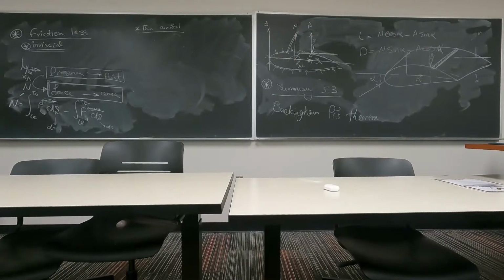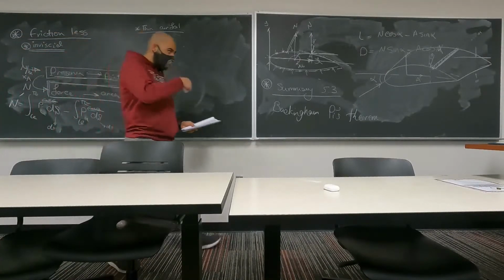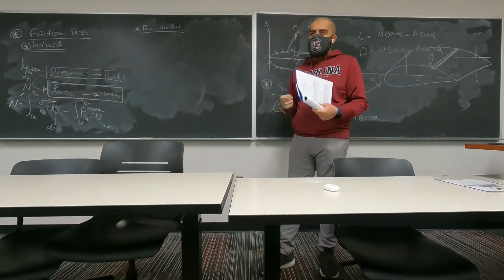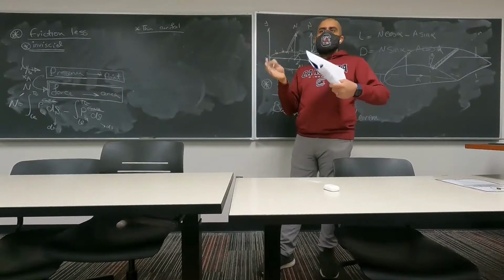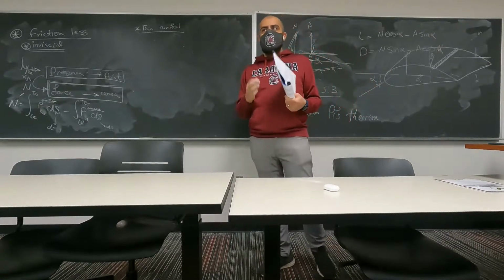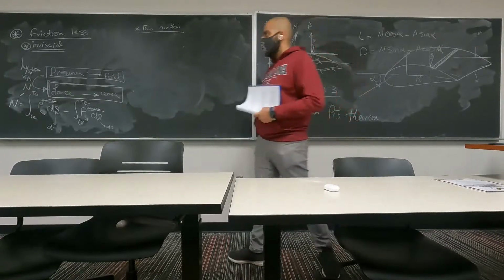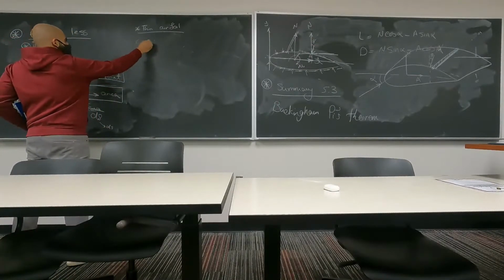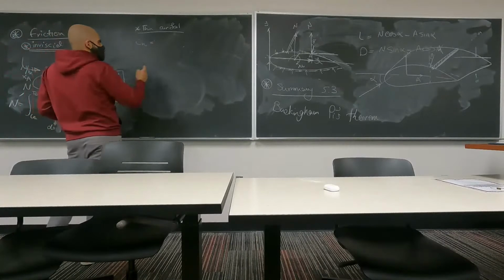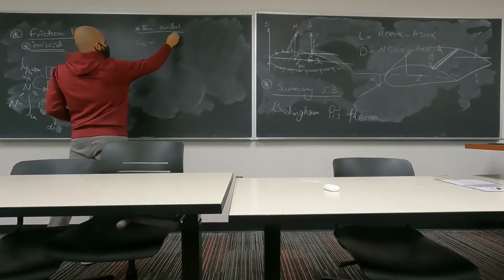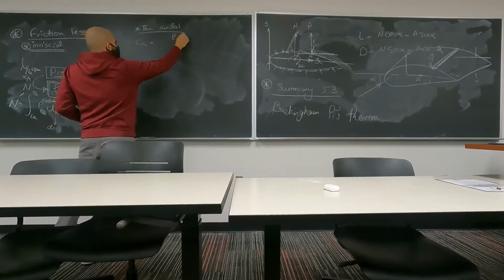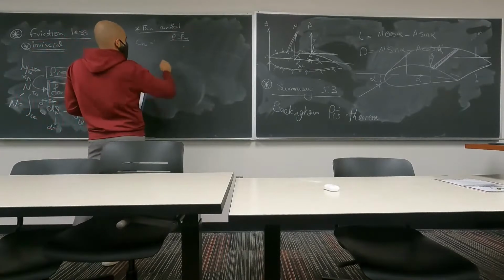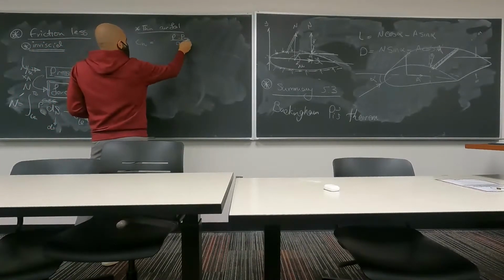S here, again, we are dealing with N prime, force per unit length, right? So your S here is going to become just your chord length multiplied by that unit depth, which is only the chord length, right? So if you divide everything by q infinity S, on this side, you're going to get C_n, the force coefficient, and you're going to get P, and we are going to subtract everything from P infinity as well.